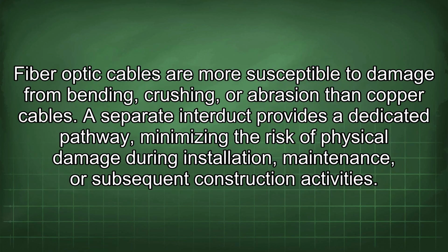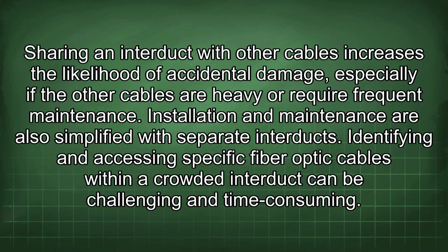Fiber optic cables are more susceptible to damage from bending, crushing, or abrasion than copper cables. A separate interduct provides a dedicated pathway, minimizing the risk of physical damage during installation, maintenance, or subsequent construction activities. Sharing an interduct with other cables increases the likelihood of accidental damage, especially if the other cables are heavy or require frequent maintenance.